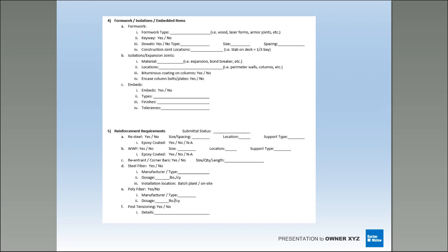Reinforcement requirements. You're going to want to sit through and ask, hey, is it a rebar steel mat that's going in? Is it welded wire fabric? Is it steel fiber or polyfiber? Hey, polyfiber, and they're asking you to do a sand polish. You as polishers out there probably know that's not going to look very good, right?